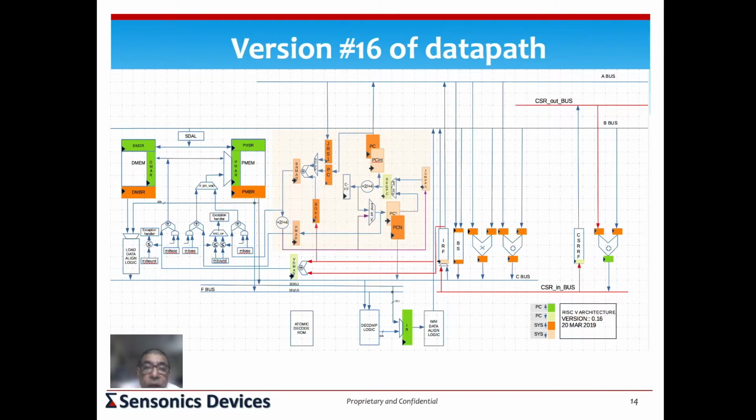How much detail should you put in and how much detail should you abstract? Up to you, your convenience. For example, in this IRF, I have not shown a control signal; for any of these I have not shown the controls. But specifically for the barrel shifter, I have not shown the count input. So the count is coming into the barrel shifter, how much you're going to shift by. That is not shown. It's a control input, right? But it's not shown here. Again, in the barrel shifter, we are showing two inputs coming in from the B bus and the A bus. So there are two potential sources into the barrel shifter, but at any point, the control is not shown.